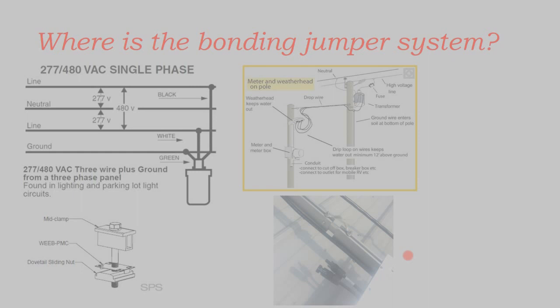Piles that are driven directly into the ground, you think, well, the ground is the ground, and that's metal going into the ground, but it may not have enough resistance to qualify as a ground path. Two pieces of anodized metal racking being pressed together does not qualify as a ground path. Grounding the racking system directly to a metal rooftop may not qualify as a ground path.